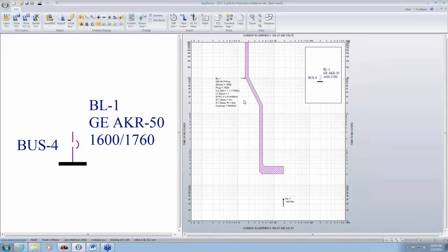For a lot of protective devices, the trip time for either the fuse or the relay or the circuit breaker would depend on the value of the current that passes through the protective device. And so the time in this case is a dependent variable, whereas the current is the independent. That's why we flip the axes this way, and this has been the convention for many, many years. If you look at the scale, you'll see that these axes are both in log scale. So you have logarithms on the time as well as on the current.